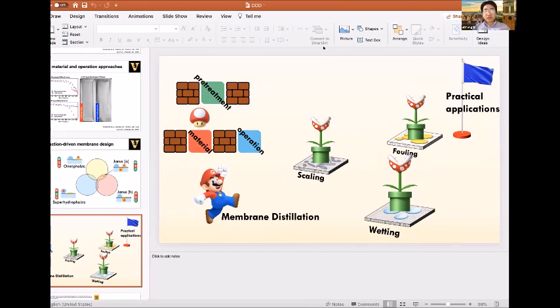Oh, that's a great question. As I said, for superhydrophobic membranes, you really just need very large roughness. Just make it really rough. For example, put large particles on the surface and then put small particles on top of the large particles, and all that. It doesn't matter what type of architecture those roughness features are. Just a lot of surface area.